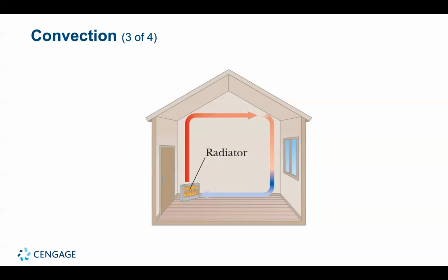That is forced convection. In the radiator, the hot water passes through metal pipes that are in contact with cooler outside air, and energy passes into the air by conduction. The cooled water returns to the engine by the water pump to absorb more energy. The process of the air being pulled past the radiator by the fan is also forced convection.